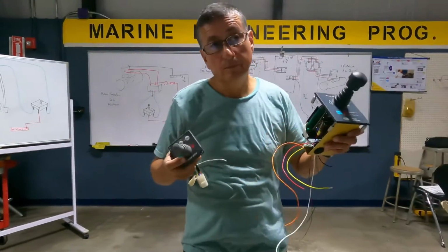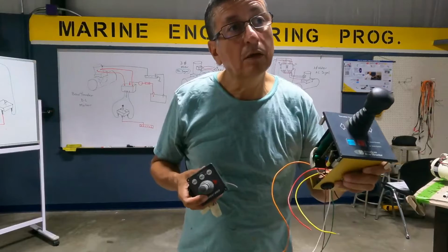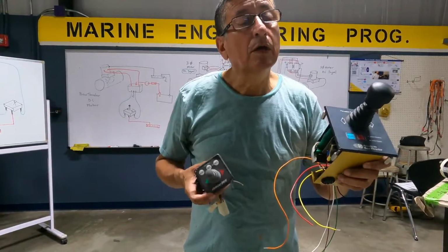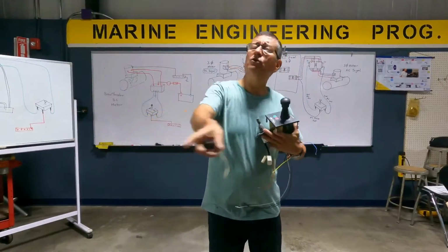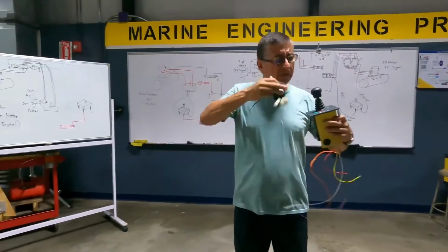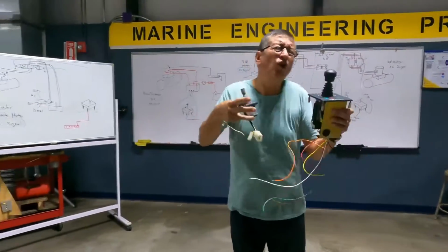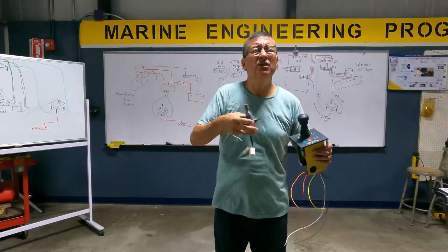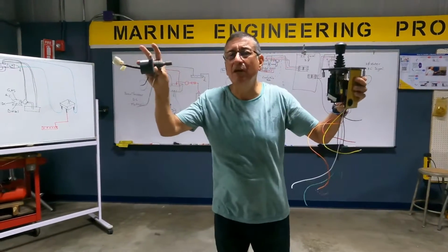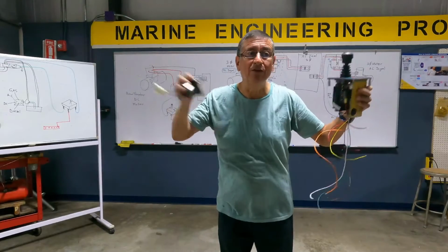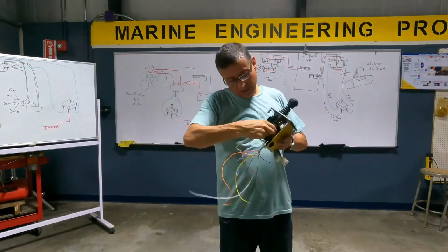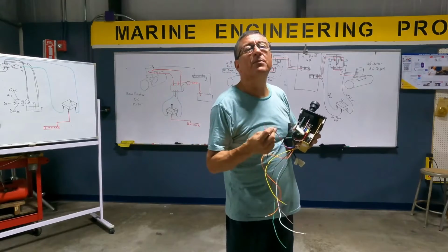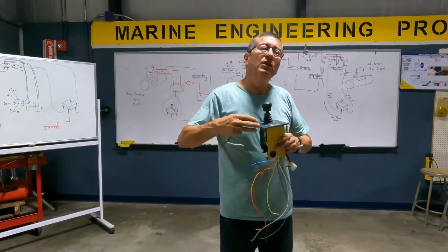Well, with that one we had to send power to get it to work. Yes, this one is supposed to have the lights on when you activate the ignition switch in the console. Not only the joystick: you have lights on the gauges, you remember, when you did the panel. In other words, this red one will be the purple from the ignition switch to activate power.